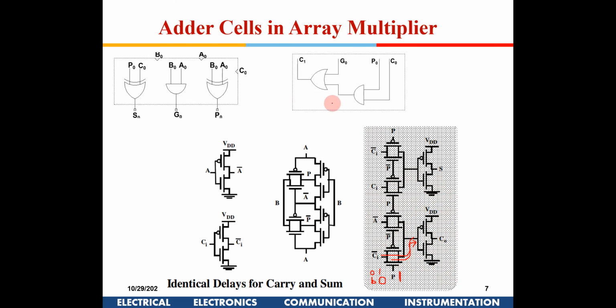In multiplier designs, instead of having a 28 transistor design and things like that, this is a better option. One, it has a lesser number of transistors. Second, equal importance is given to sum and carry, so they come out together, because sum is also equally important for multipliers.